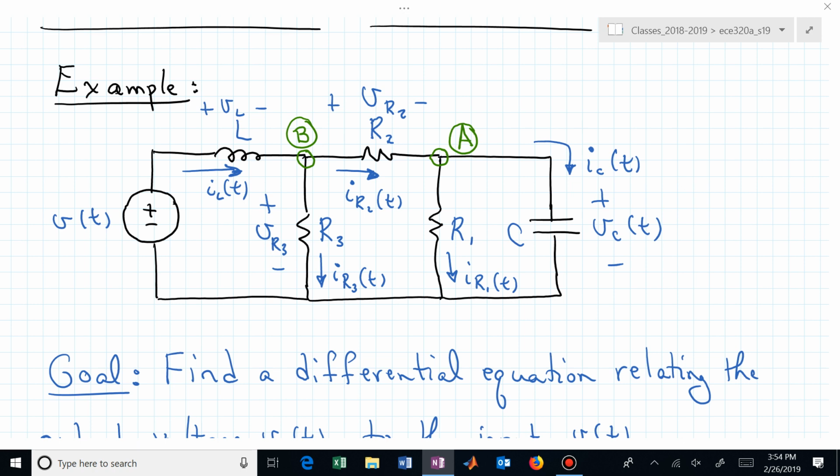If they were two real roots, then they would both collapse. What I was expecting you to say was, well, it's a passive circuit. It should just exponentially decay the response or that voltage. How it exponentially decays obviously is influenced by the inductor, capacitor, and those resistors. But generically, you could say, oh, it's going to be an exponentially decaying response.